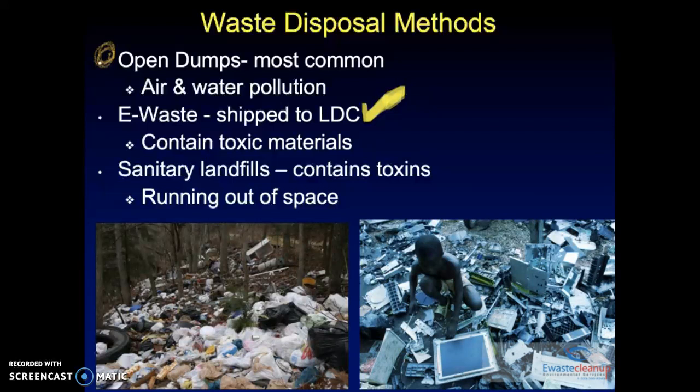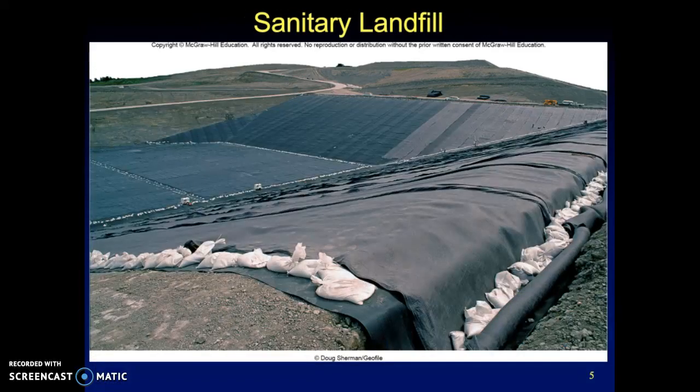Chromium, other things that are just not safe to be around. The goal for waste disposal method are the sanitary landfills. Okay, this is a big giant pit. If they're built correctly, they're lined with impervious layers that won't leak. And waste gets dumped in there and dumped in there and dumped in there, and it piles up, and then we cover it with dirt. We basically cover over the top of it and seal it up.